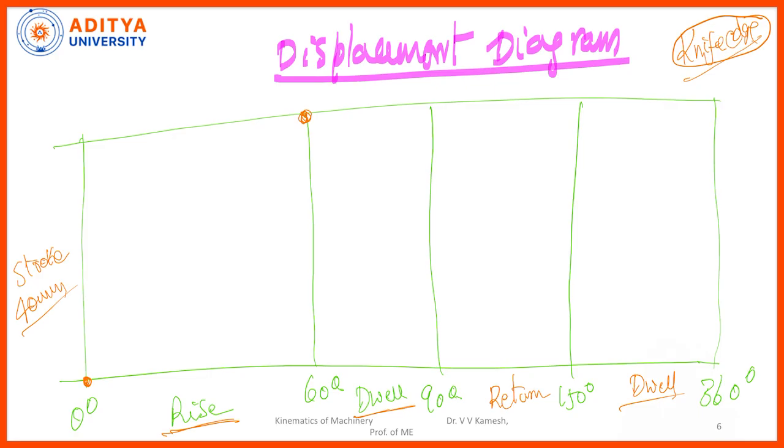to travel 0 to 40 mm, it is taking cam rotation 60 degrees, right. Now, okay, I will take this as the O point, this is point A, this is point B, now this is the point C I will take, and this is again point O, because it is to repeat, right. I should not take the point D, right. Again after 360 degrees, again we are coming to the same point, that is why I am taking, this is also O. Now, you look at this, O to A, what is the path it is to follow?